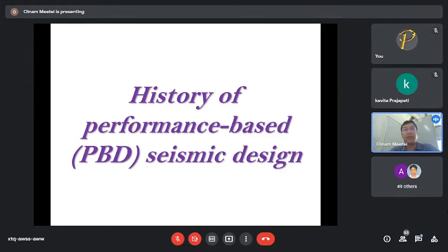And the point of the previous slide was the overall design concept that we use in current day-to-day life. As a faculty you have taught reinforced concrete design, or maybe as practicing engineers you did lots of consultancy projects, and you did beam design, column design and frame design. Everything you focus on that code. IS 1893 is the only code giving the seismic load, and after applying the seismic load, whatever bending moment and shear force come up, you design for them based on the IS 456 criteria.